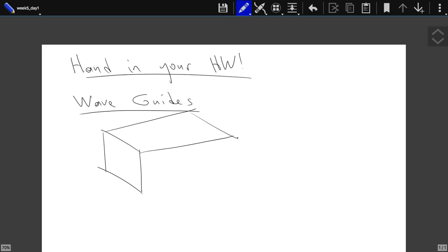This is your waveguide. Of course, we have seen that if the metal is very thin, it will not confine the electromagnetic field, but it should have some thickness, at least a couple of skin depths. We have seen that if you send an electromagnetic field on a conductor, it still penetrates to some extent, which we call the skin depth.